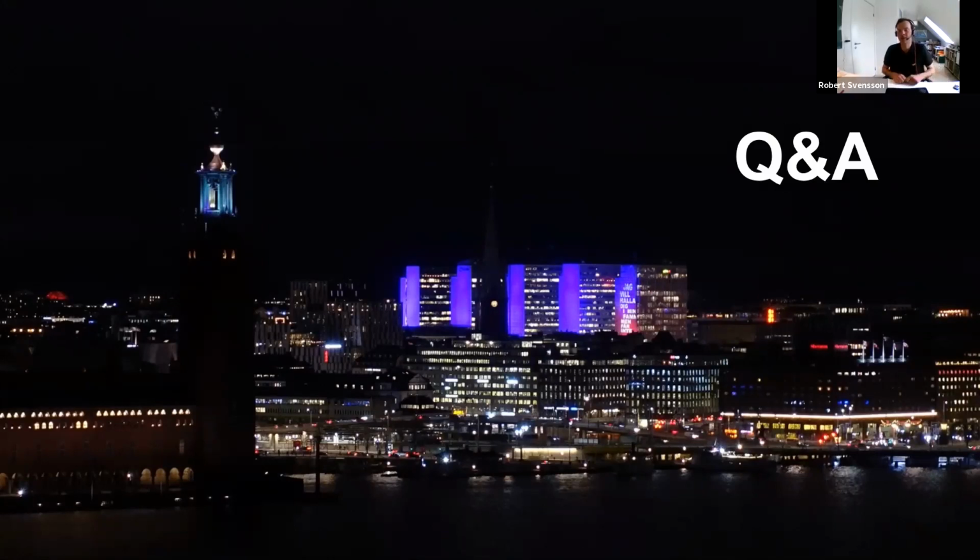Of course you can change gobos. It is actually rather easy, but you need to go on site. You need to open the fixture. There's a process for inserting the gobos and securing the fixture again, making sure that it's correctly sealed and that no humidity is trapped inside the product. So the product is designed for it, but it's not something you would do every day or every week, not at all. But you might want to do it maybe every half year.